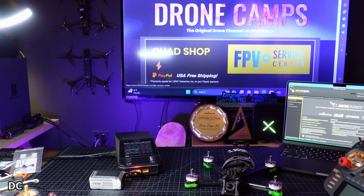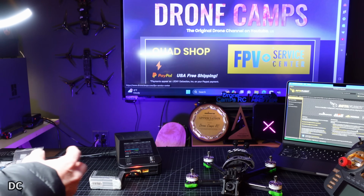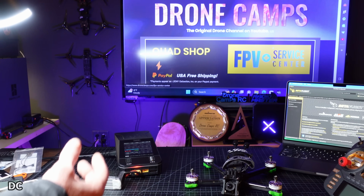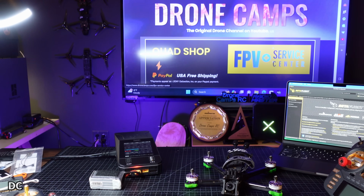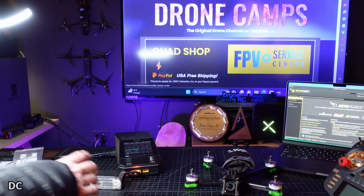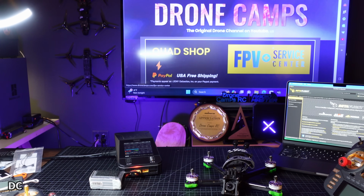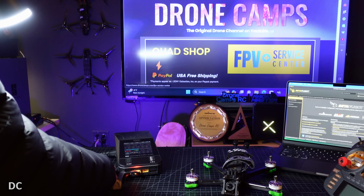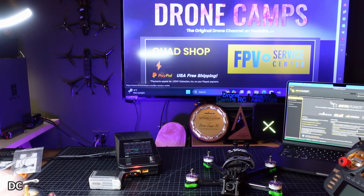I know I have friends that have lost entire lifetimes of all their RC airplane stuff, their four-wheelers, their truck. I had one guy who burnt down his garage. I've had other people lose their entire house. So be very careful when charging your LiPos. Another big tip, aside from never leaving it unattended, is to walk by it every once in a while. Just put your hand on it and feel it. Feel it with your hand, and just feel if it feels hot.